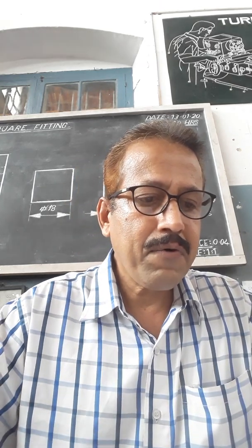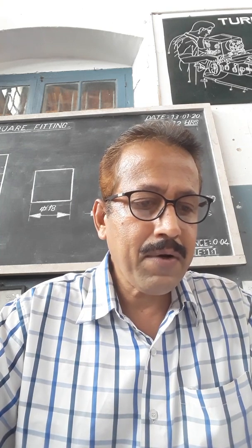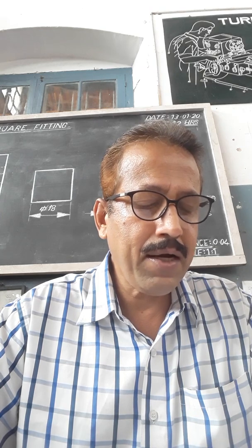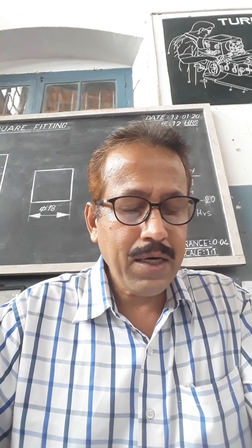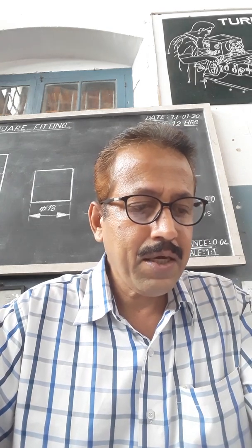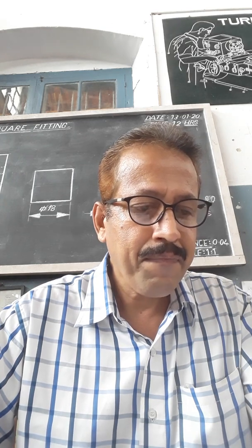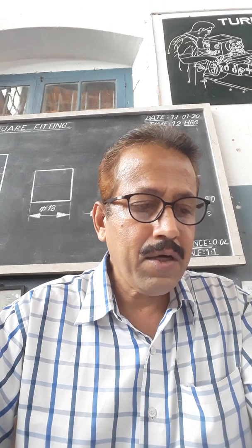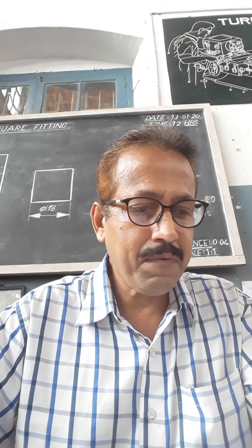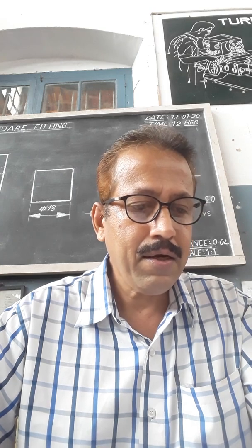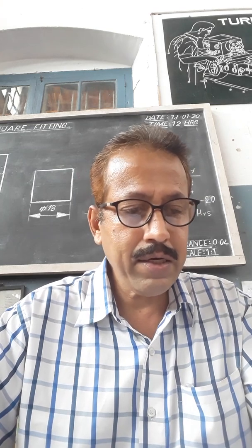Compare this deflection force with the range of forces given in the table. If it is less than the minimum recommended deflection force, the belt should be tightened. So if the force is less than the minimum recommended, then the belt should be tensioned. If it is more than the maximum recommended deflection force, the drive is tighter than it need be, which means the drive is too tight and tighter than needed.